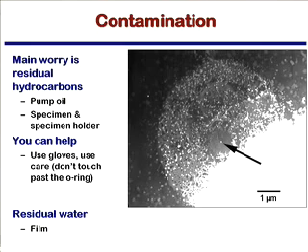Yes, Leor? If you let the beam raster all the area uniformly, you can avoid it or minimize it. So he asks, what happens if you raster the beam uniformly? Well, what you then get is a uniform level of carbon contamination over a square. Well, it's thin, but if you're rastering continuously, it will thicken up as well. If you use the SEM, which again, some of you all take an SEM class, you'll notice that it's not uncommon at all to see contamination local to the area you've been imaging for quite some time. And it's the same effect. It's the residual carbon piling up where you want.